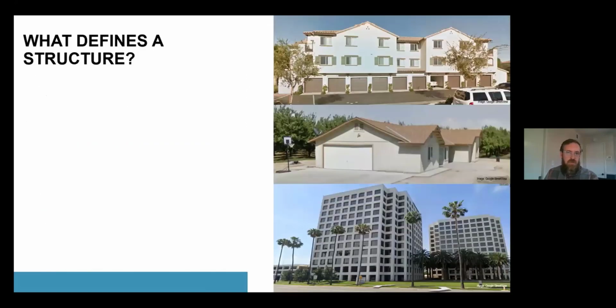So what defines a structure in the structure inventory? There's a few examples here in different structures: multi-family housing, single-family housing, and commercial or industrial structures. So the first thing is the number of stories. How tall are each of those stories, the height, so we know how it compares to the depth when people are impacted by the water. In addition to that is the foundation height. How high off the ground is that structure set? Do you have access to the roof or an attic?